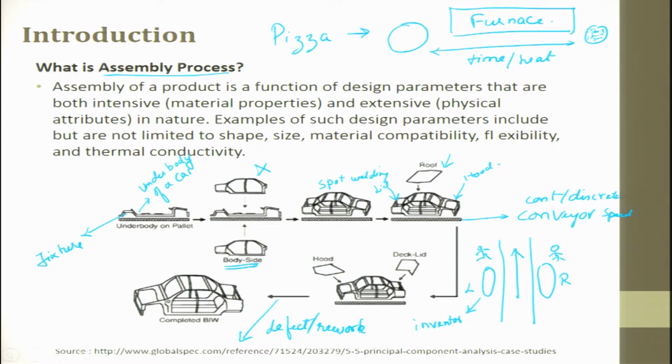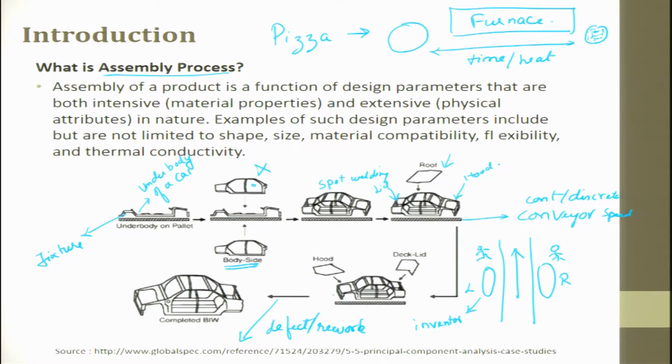This is also possible: if it is only one defect and it is peculiar, which is not going to get continuously repeated, then they say okay, let it go, and then we will pull it out and rework only that car, but the rest let it go on the fresh one. Suppose there is a major defect in the metal working operation, a hole or a dent, then the entire car is pulled out and reworked, and the rest of the assembly, the car goes through every station, spends that time, and no work will happen on the car.